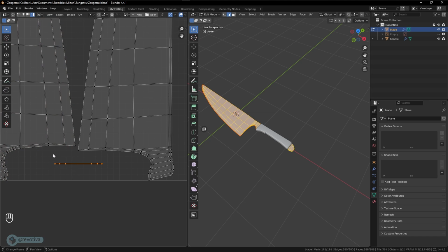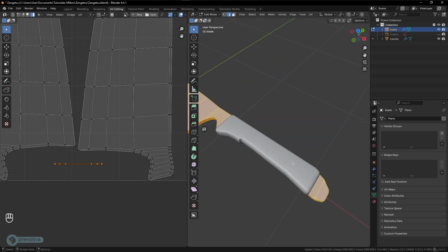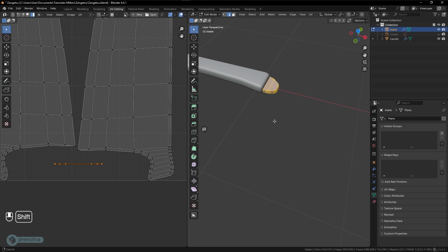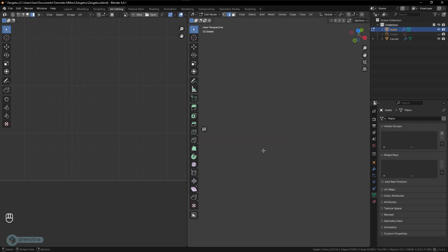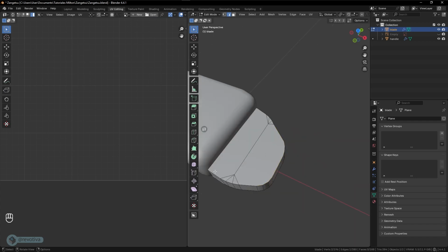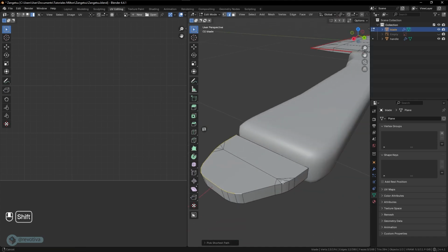It's got a bad UV unwrap, so I need to press edge mode, select this loop selection, and select this, and with Control click, no, it's following this line, so I will select one by one, or maybe select this and then this, pressing Control left click.